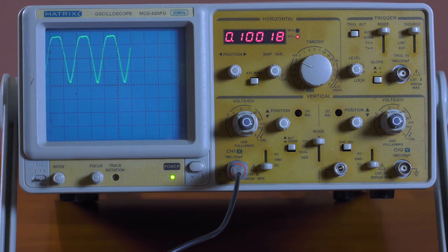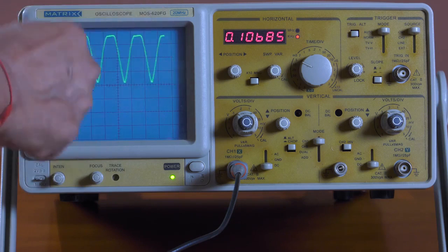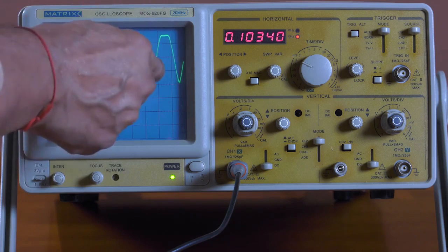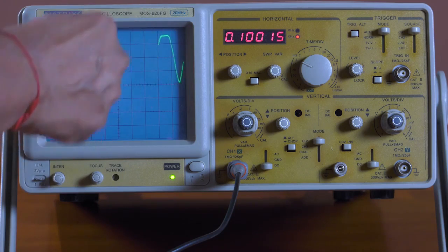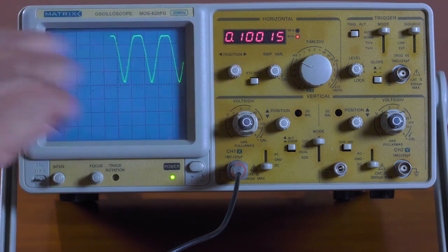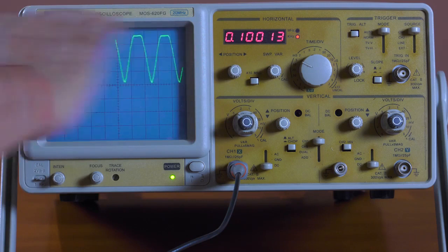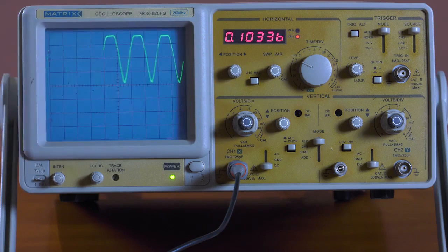All we need now is to remove this thing called pulsating DC. This is called pulsating DC. We need to get rid of that. We need to now make it a straight line DC like we saw with the battery that we used. And the only way to do that is to add in filtering circuits where we use capacitors.